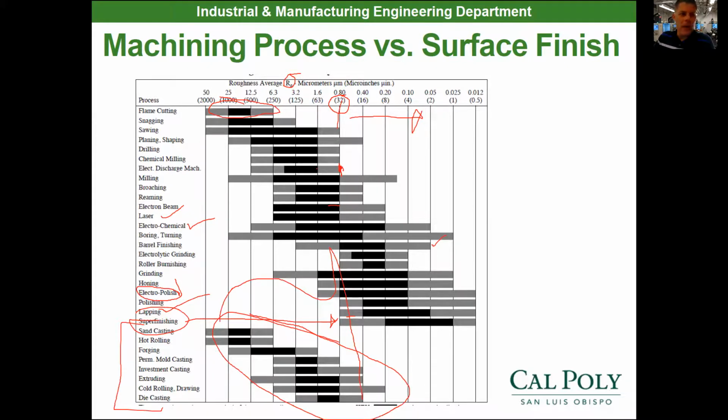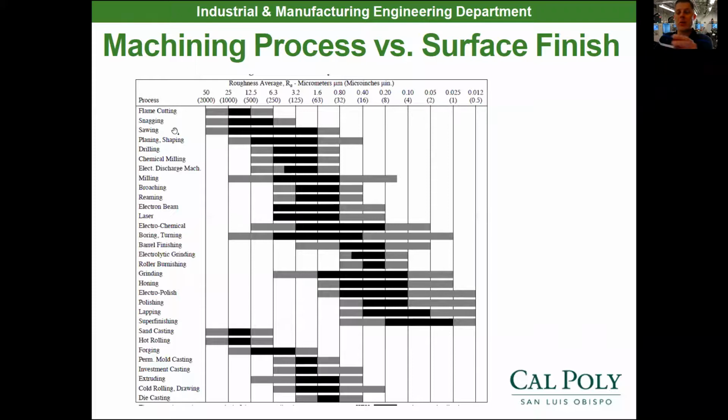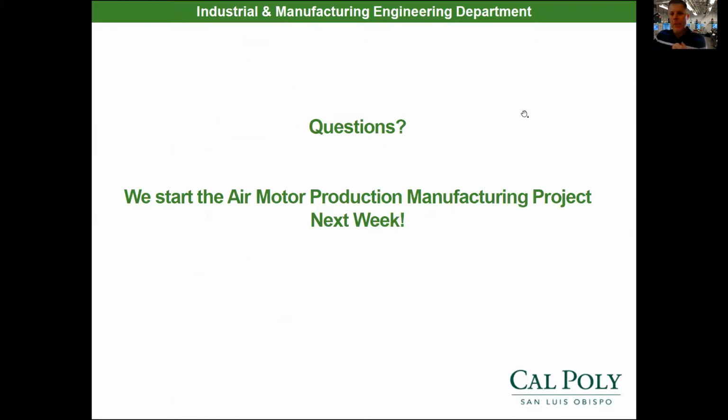So I know you've learned a lot about machining. We're going to continue to do it over the next 3 weeks before we take that final exam in week 10. But I hope you had a great week learning about abrasive processes. Remember, if the workpiece is too hard, we've got to cut it with an abrasive. If it's got a really fine surface finish callout, or if it's got a tight tolerance requirement, it's got to go to an abrasive process.